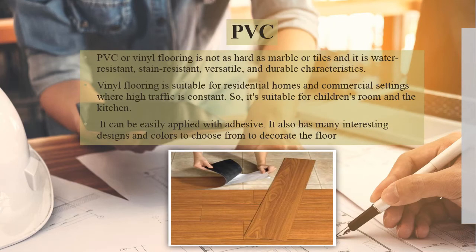Types of floor finishes. Number 3 is PVC. PVC or vinyl flooring is not as hard as marble or tiles, and it is water-resistant, stain-resistant, versatile, and durable. Vinyl flooring is suitable for residential homes and commercial settings where high traffic is constant, so it's suitable for children's rooms and kitchens.